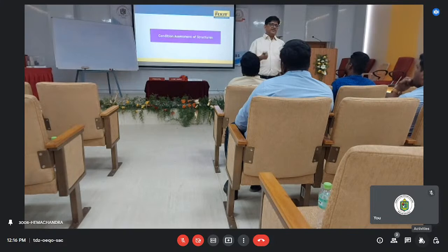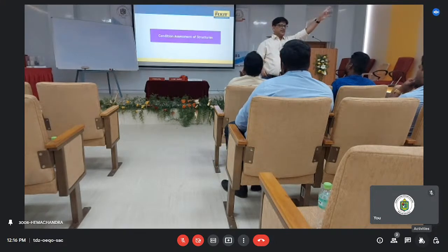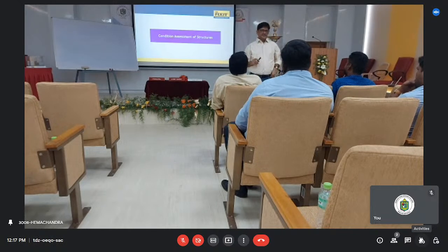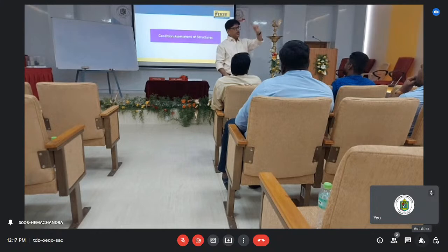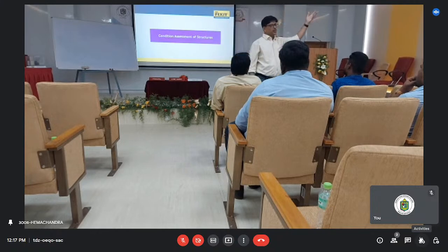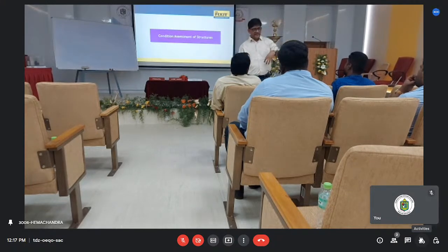Grouting may not always be a solution, because if the source is not taken care of, the water will come from somewhere else tomorrow. The source is always there. Until I have gone to the source, I will put some grout on the negative side and finish it off, and again one fine morning it will start. It has gravity: if it is coming from the top, it has to go out somewhere. It will always find its own way.